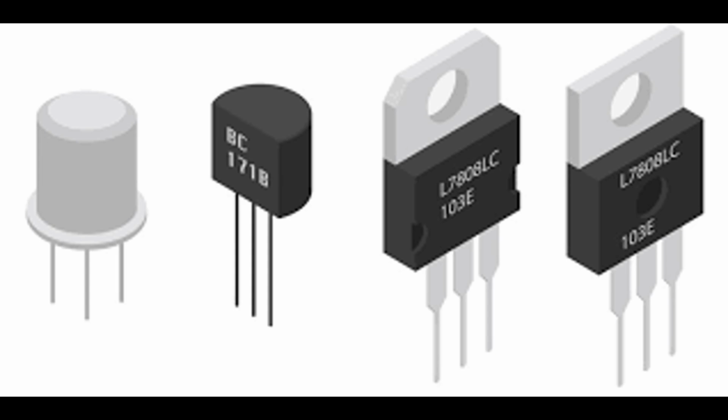Single gate control, requires only a single gate signal to trigger conduction in either direction. Latching device, remains in the conducting state once triggered until the current falls below the holding current. Sensitivity to dV/dt, requires careful circuit design to prevent false triggering due to rapid voltage changes.